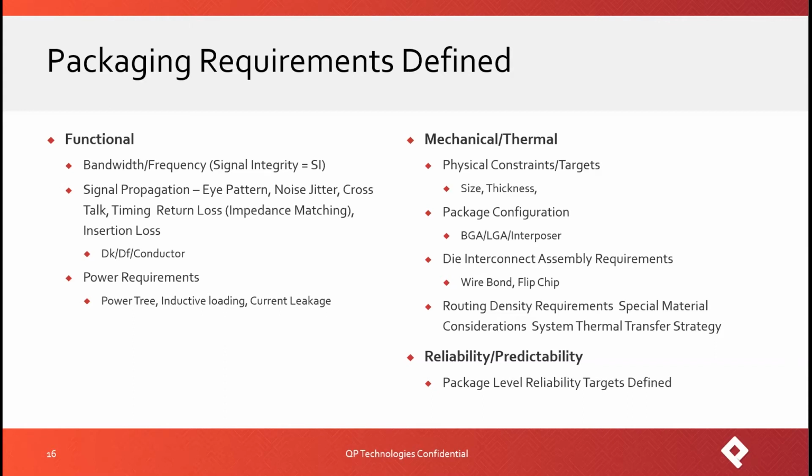From a cost and manufacturability point of view, if volume manufacturing was ever a consideration, high volume manufacturing or cost, certainly QFN is your answer. The problem QFNs run into is die size as well as lead count. In essence, the 12 by 12 is about as big a package as you can get that will be able to reliably attach to a PCB board for long-term reliability because of the DNP of the package. When you get to higher lead count, really BGA is the direction to go.